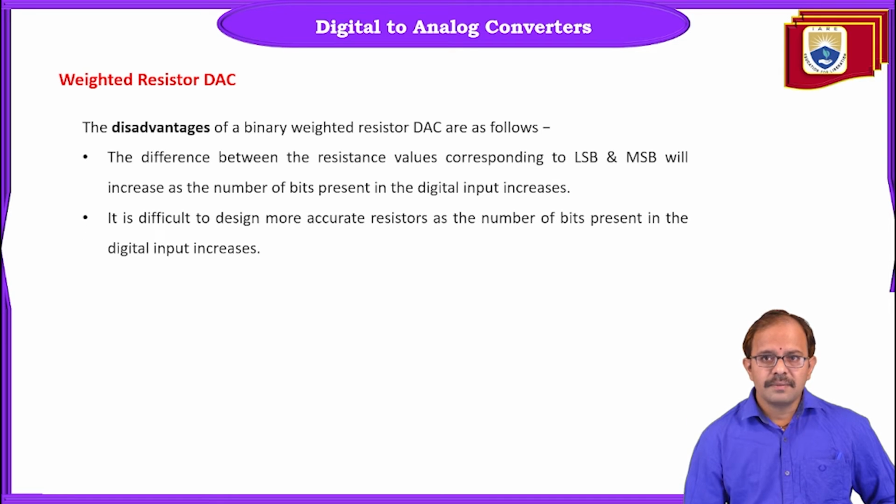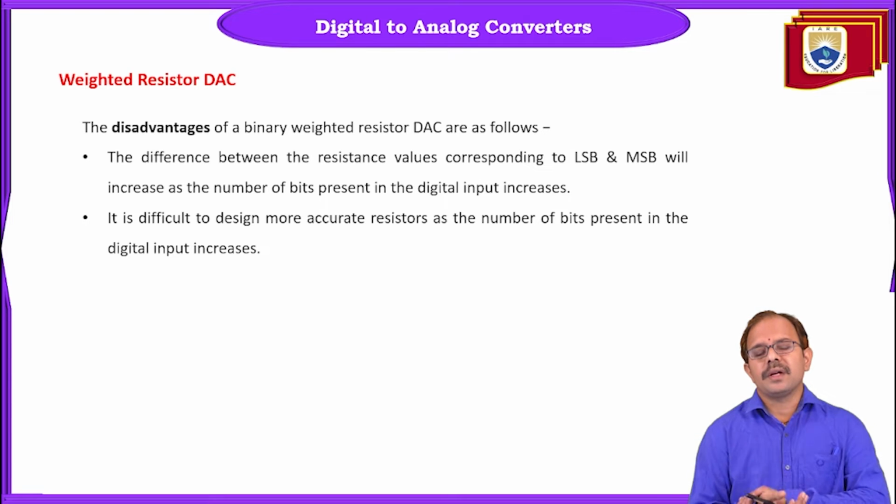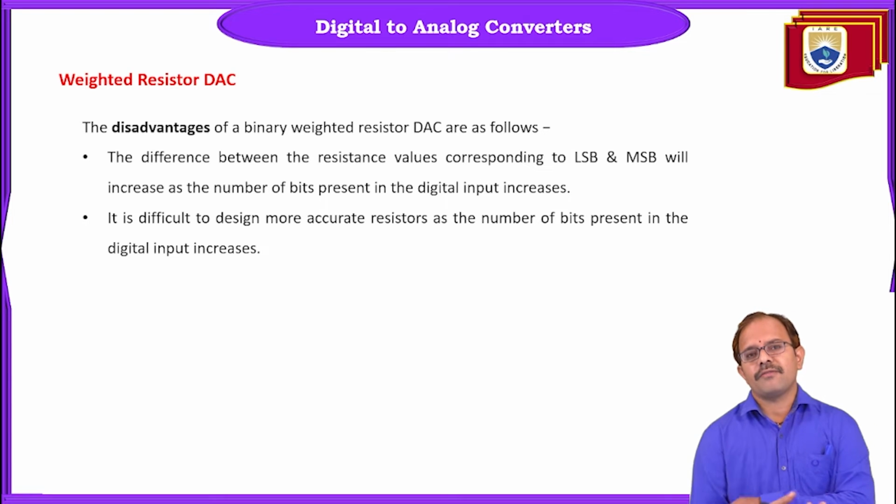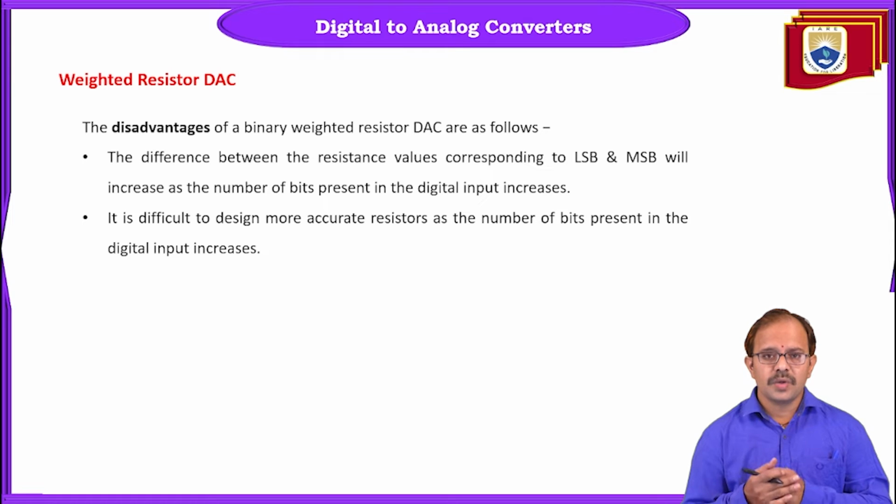And we need more resistors to build this weighted resistor network, and these resistors are of large values. It is not 2 or 3 or 4 resistors. The resistors are huge in number, and their values vary abnormally. That is, the difference between any 2 resistors is quite large.